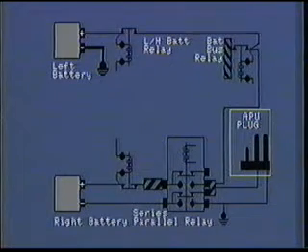The APU, an additional source of power, is also connected to the aircraft electrical system through use of the battery switches. There do not, however, have to be batteries installed for the APU to be placed online.